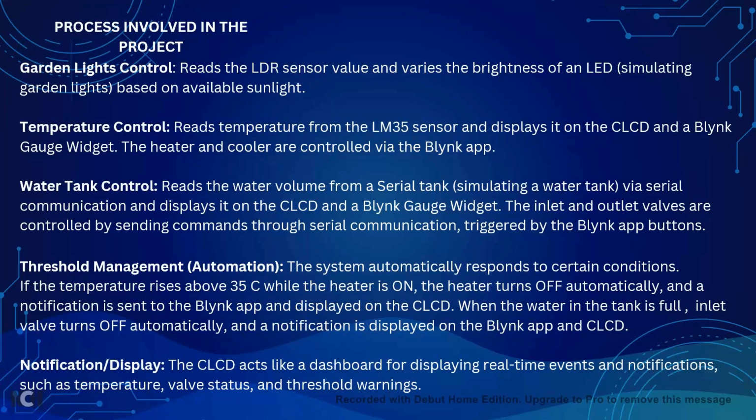Water tank control: reads the water volume from a serial tank, simulating a water tank via serial communication, and displays it on the CLCD and a Blink gauge widget. The inlet and outlet valves are controlled by sending commands through serial communication triggered by the Blink app buttons.